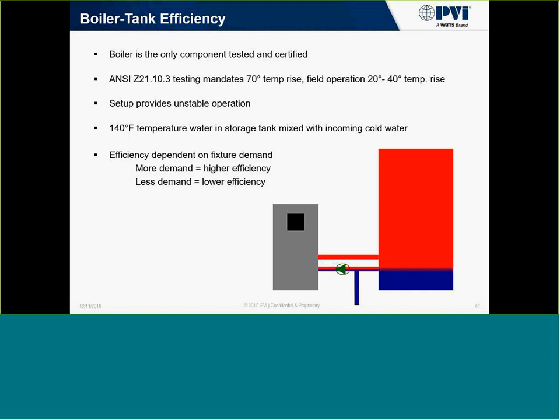With us taking that 15 GPM out of that tank, pre-mixing it and throwing it through that heat exchanger, we are no longer feeding it with the coldest temperature possible under those low flow or low demand type situations. And that's why under those low demand situations we have a lower efficiency of that boiler, because we're not feeding it 70-degree water anymore. We're probably feeding it closer to 120, 115 at best, if not even higher. If that storage tank's stored at 140, we could be giving 136 degrees right into that heat exchanger. So in those type of situations, it's physically impossible for those boilers to condense.